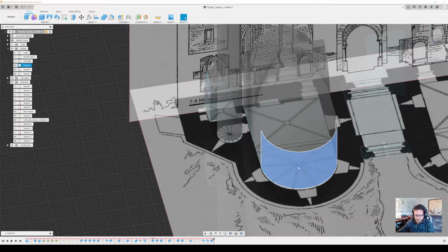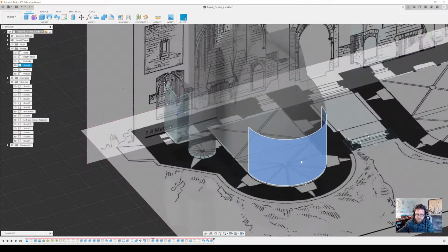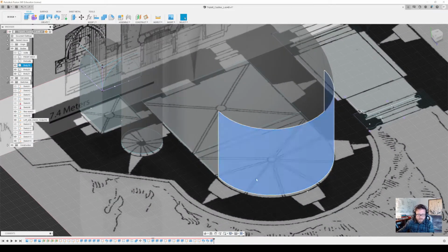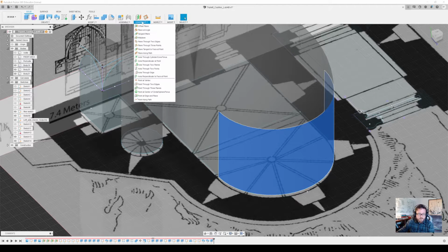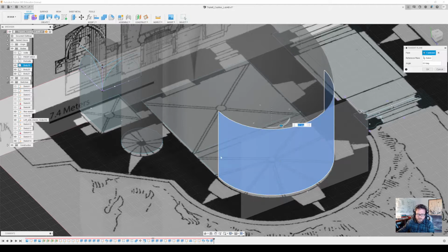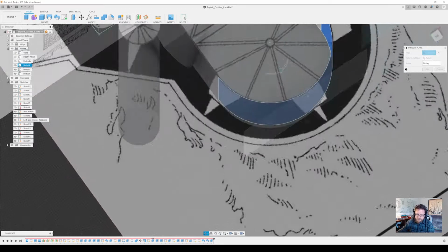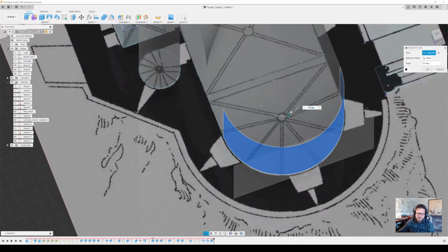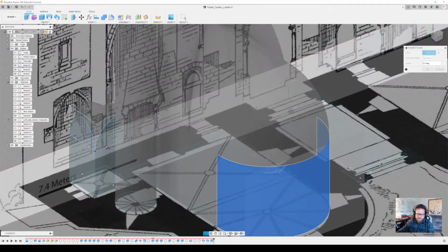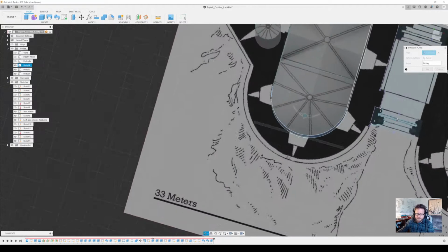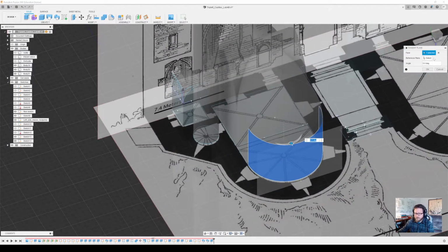We're also going to do this one right here. So the quick step for that is you're going to create a tangent plane because you need something to draw on. You're going to draw this one first, and you just need a flat plane in order to draw on anything in this software. So we're going to go to construct, tangent plane, and if you selected this curve tool, it's going to put this at 0 degrees, which is dead center. It's possible it may ask you to turn it 90 degrees, but it should be right, and it should look about like that. That's fine. I'll hit OK.